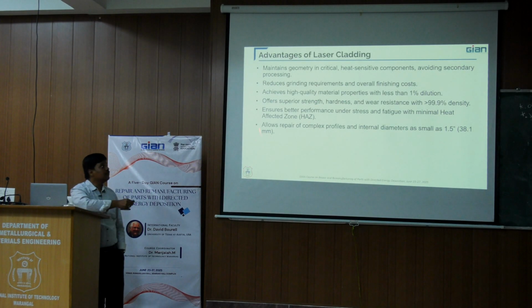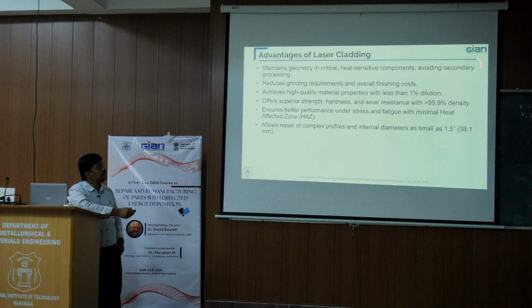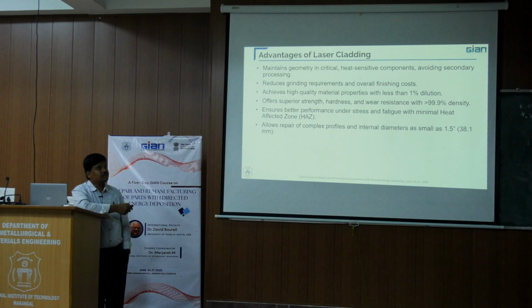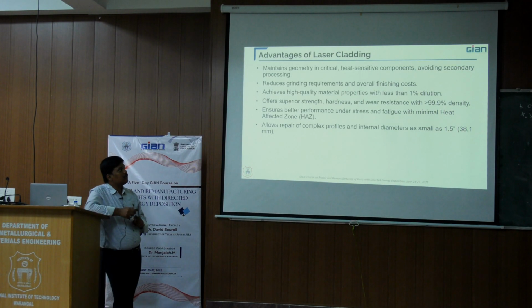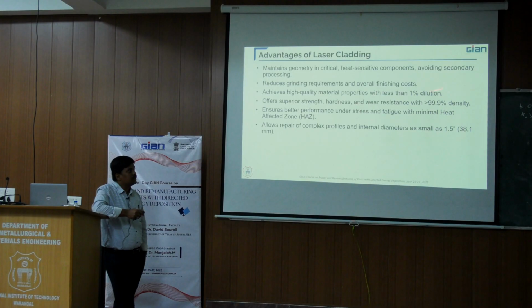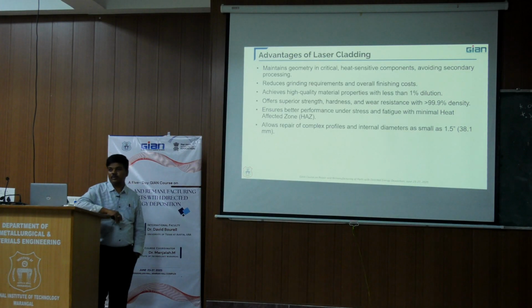But the main advantage is that we can maintain the geometry of critical and heat sensitive components, and avoid secondary processes. We can minimize additional processes, reduce the grinding requirements and the overall finishing. The overall cost of manufacturing is minimized, and we can achieve high quality material properties with less than 1% dilution. That's what is possible with laser DED cladding and other repairing aspects. It also ensures a minimal heat affected zone.